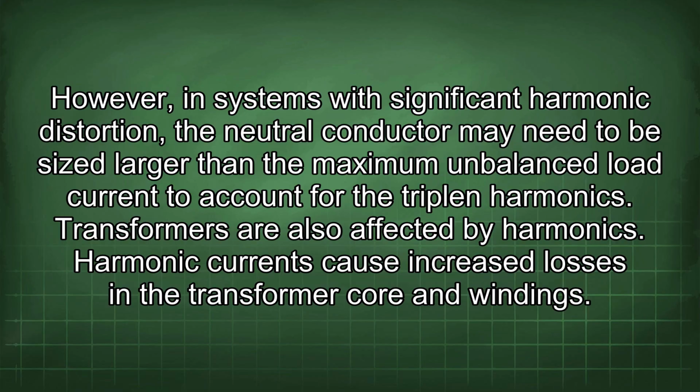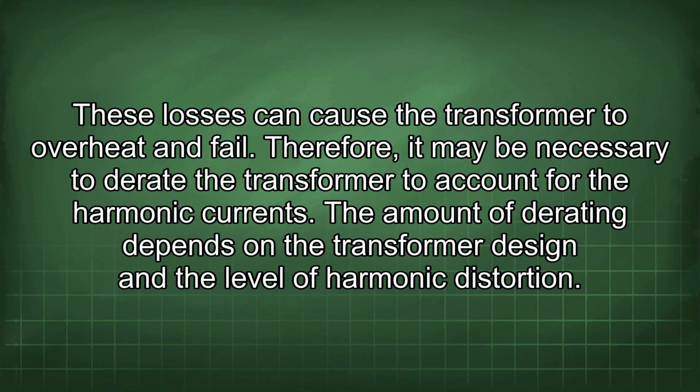Transformers are also affected by harmonics. Harmonic currents cause increased losses in the transformer core and windings. These losses can cause the transformer to overheat and fail. Therefore, it may be necessary to derate the transformer to account for the harmonic currents. The amount of derating depends on the transformer design and the level of harmonic distortion.